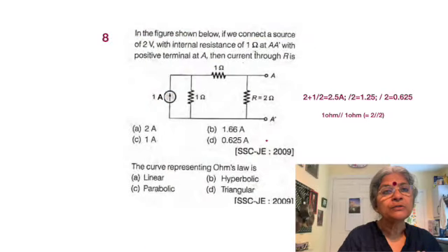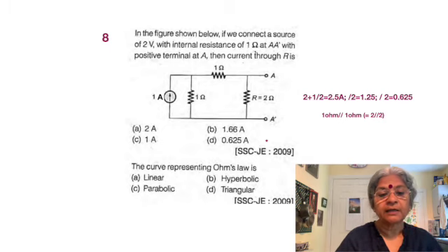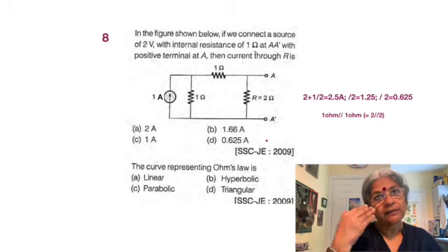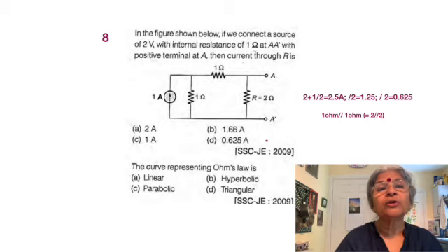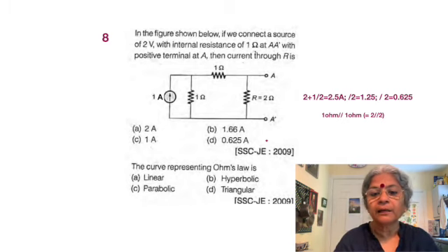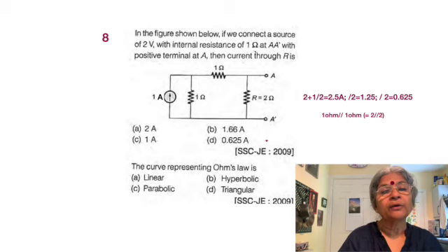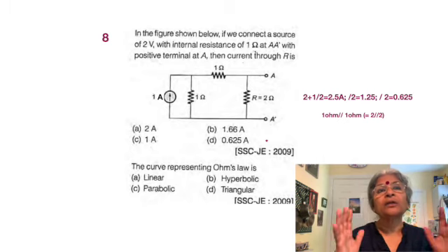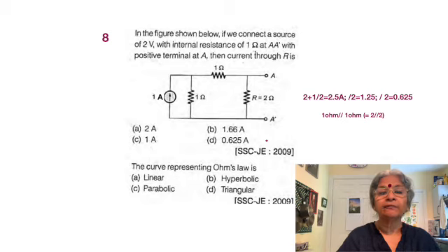So I'll just repeat a little. We work from the left side. We convert the 1 ampere source to a half ampere source after 2 transformations. First is the voltage transformation, and then there's a current transformation. Now we are having 2 ohms in parallel. On the other side, we just connected a 2 volt source with 1 ohm, so that was another 2 ampere source with 1 ohm. So now we are having 2 1 ohms, and the total current is divided between the 2 1 ohms. Thereafter the 1 ohm created out of paralleling 2 ohms, the current is again divided into 2. That's all.